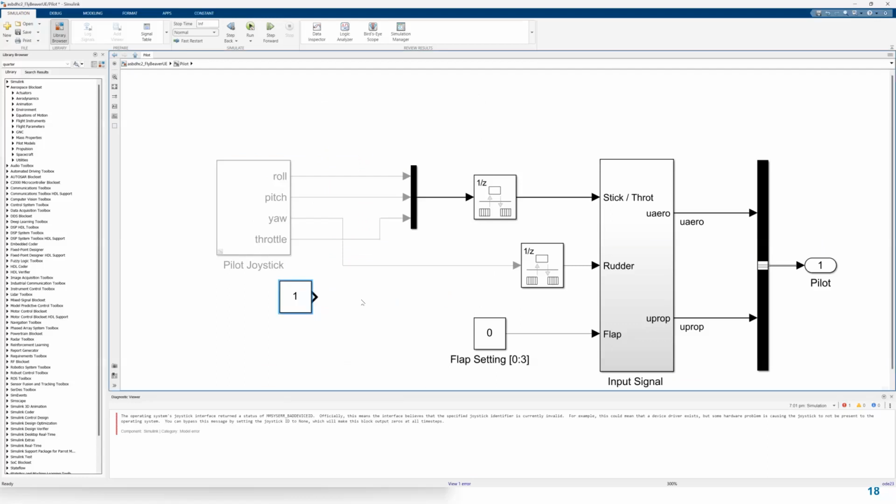And let me bring another control. So I'm giving a constant control. Let me give a throttle 100% control. So simply I'm just connecting this one. And similarly, I'm copying this and I'm telling that, okay, I don't have any roll, pitch or yaw. So I know it won't be a straight line motion, but this will result in a coordinated turn, but it's okay. We are more interested to see how the simulation is. So let me make it 0, and I did it. And now it's time to run this model.